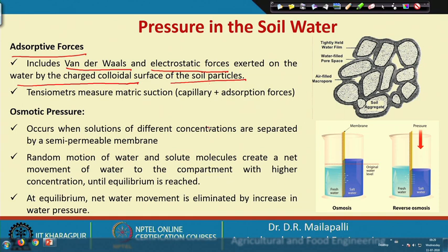So, that is electrostatic forces and also van der Waals forces. That all combines to help in attaching the water molecule to the soil, that is adsorptive forces. So, the tensiometer is generally used to measure the matric suction, which is capillary and adsorptive forces. So, both capillary and adsorptive forces will be measured with tensiometers.